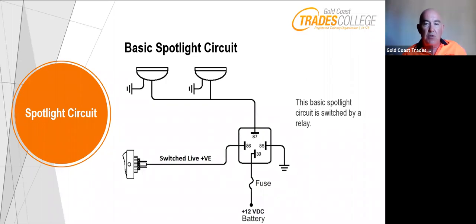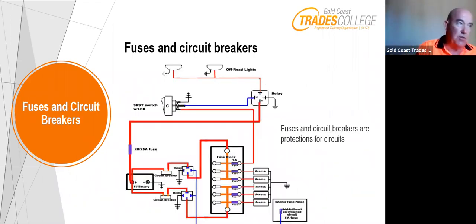On the bottom of the relay, you have these numbers, and they usually indicate where they go to. Usually when you buy it, like most things, we get a little diagram or an instruction booklet, what connects to where, and hence the terminals on the bottom of the relay have numbers beside them. So you can see it goes to a 12-volt battery, the switch, and negative. Okay. We need to complete that circuit by using the body of the car as the earth return to the battery. Okay. Let's have a look at the fuses and circuit breakers.